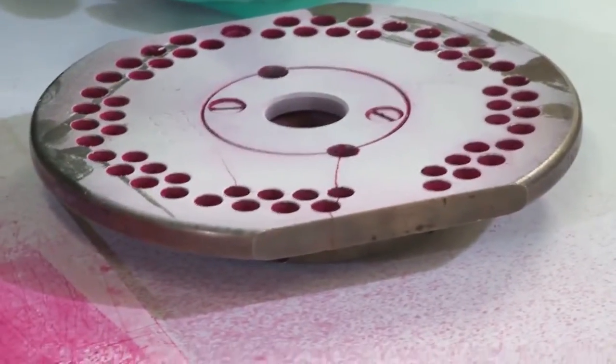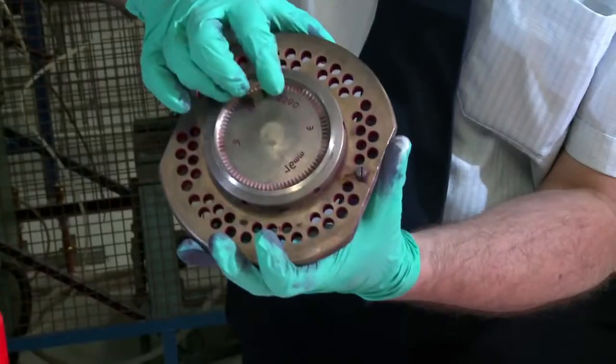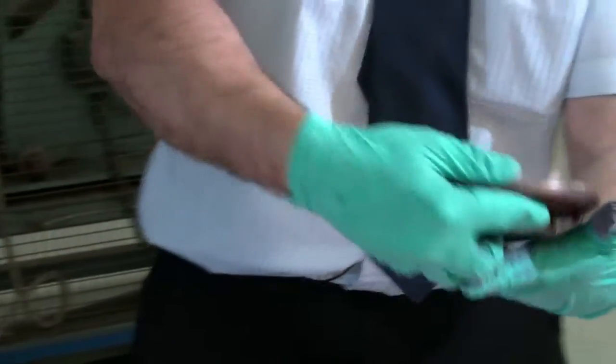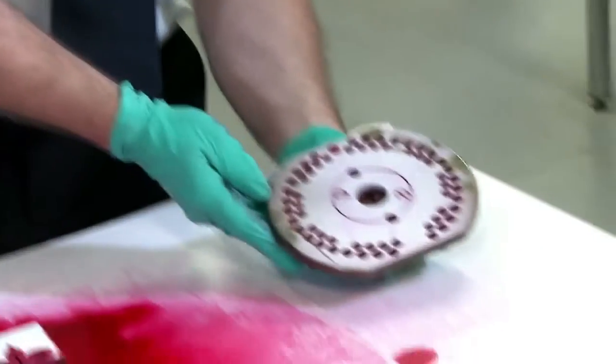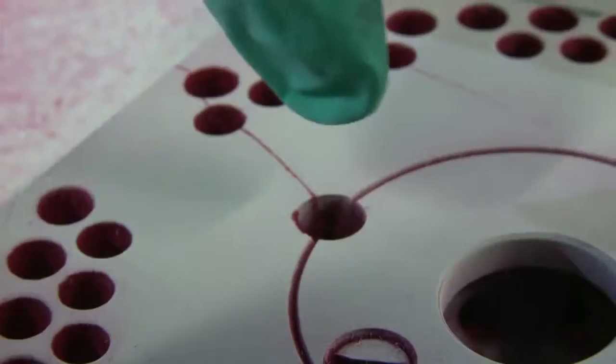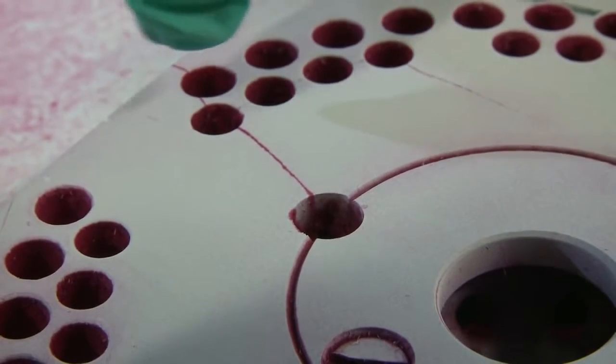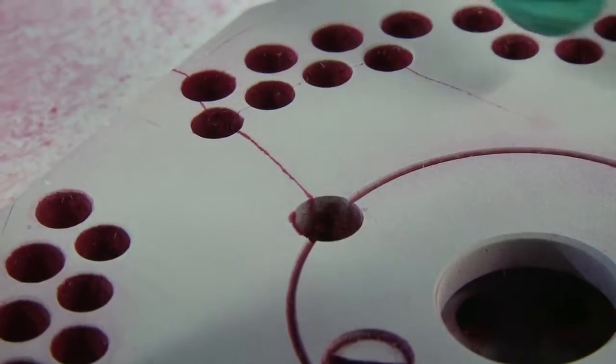What we've got here is one that came in from testing. This is a real life component. This is the bottom of a glass mould, and on the back of that we've done a dye penetrant test, and you can see about 4 nice fine cracks that run all the way through that specimen. Okay, so that's dye penetrant testing, a very nice, cheap and quick way of detecting defects without damaging the actual component or material.